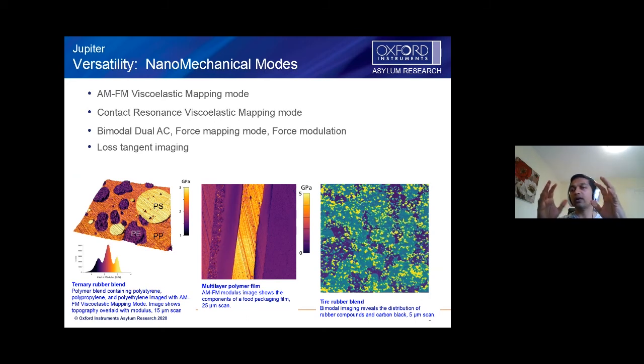The difference between a standalone nano indentation instrument versus an atomic force microscope used for doing indentation experiments is that in a bulk nano indenter, the forces are usually much larger, but at the same time, you don't have to worry about a cantilever that flexes. I don't know if you can see my video, to the person who asked this question, but in an AFM, you have a cantilever that pushes into the surface and it flexes. In a nano indenter, you have a vertical diamond tip that comes down and pushes onto the sample. So data interpretation in a bulk nano indentation system is easier.